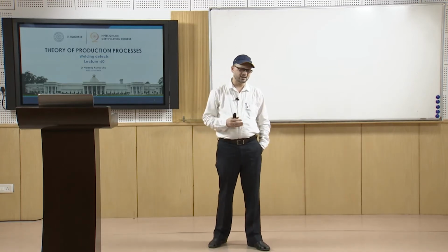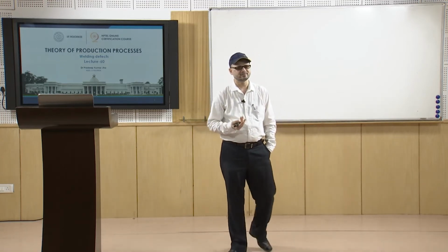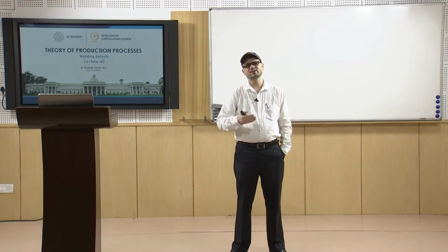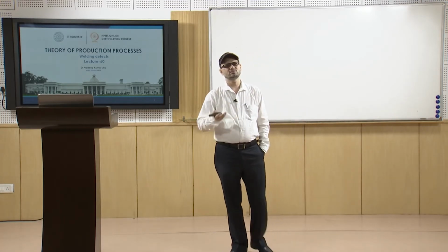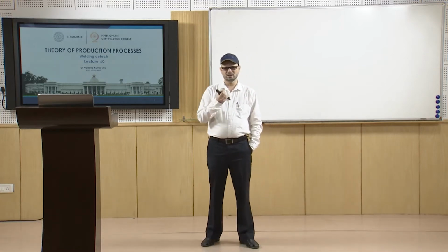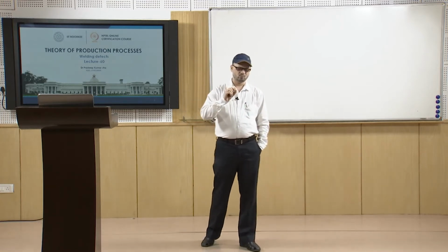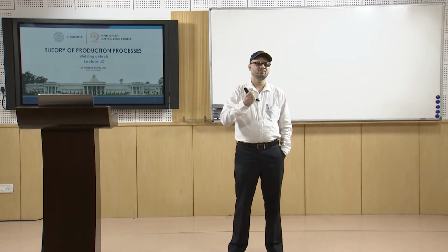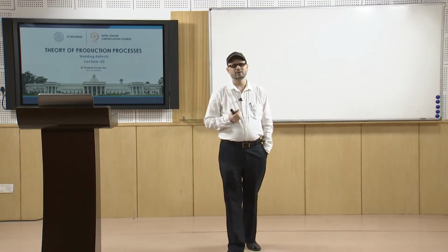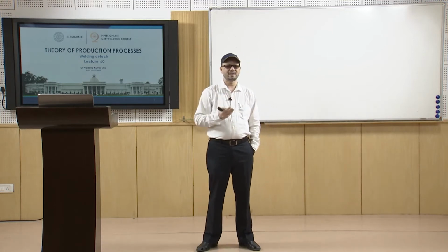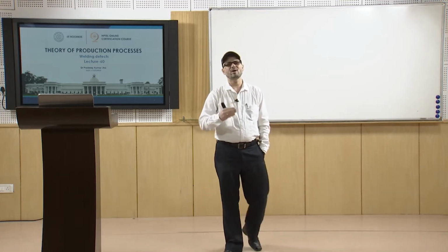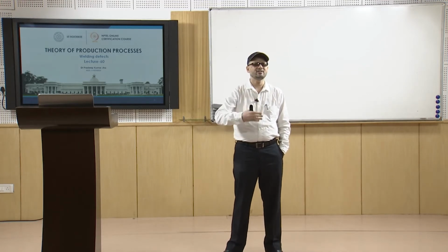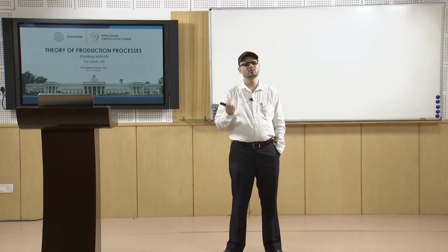Similarly, defective welding equipment. Many a times the equipment itself may be defective. Like if you are having a welding torch, the torch may be worn out, or the torch diameter is not appropriate, or the valve which is opened so that the required amount of gas flows, and is ignited further, is not working properly.